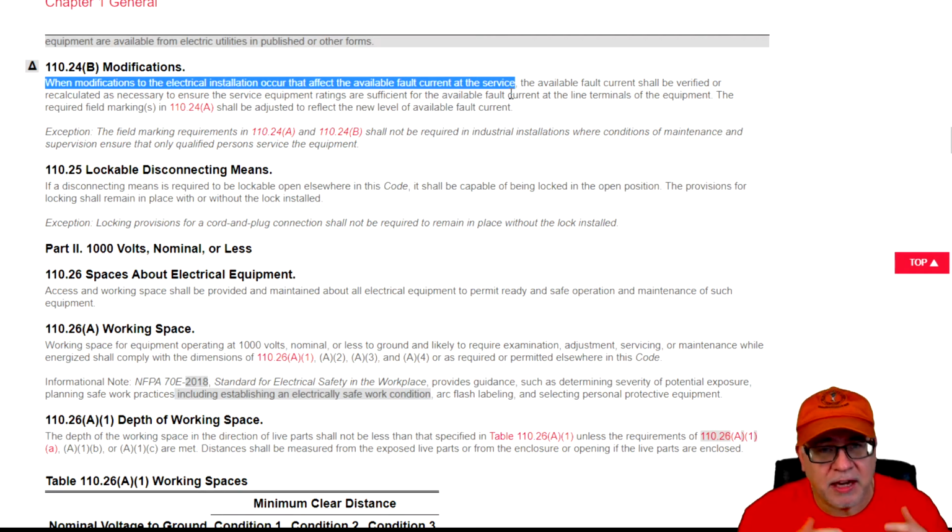Then they started a second phase of construction, and they added this second side, this other side of the development. Now they need to increase that transformer because they didn't anticipate the capacity, or they didn't have the bigger one available at the time, whatever the reason. When they change that transformer, they now change the characteristics, and it affects the available fault current at the existing setup that you calculated for that old transformer. So now things change. So we have to be real clear that things get changed, things get modified, and we have to be aware of that.